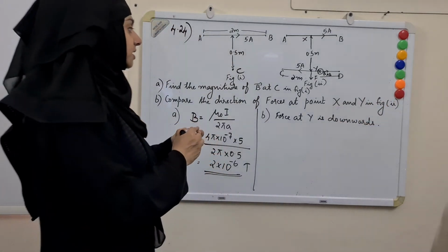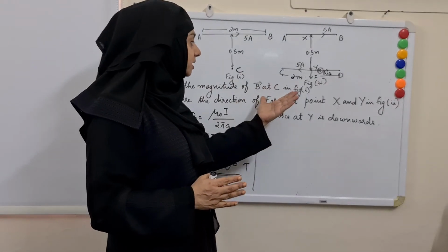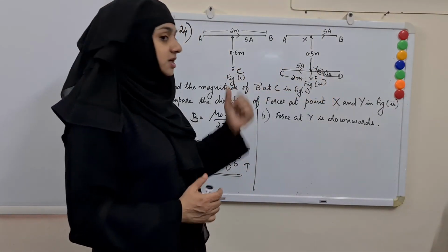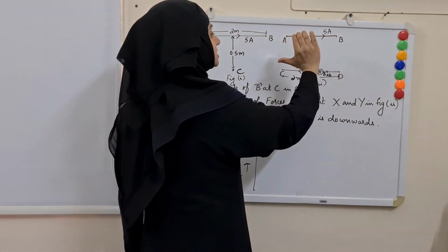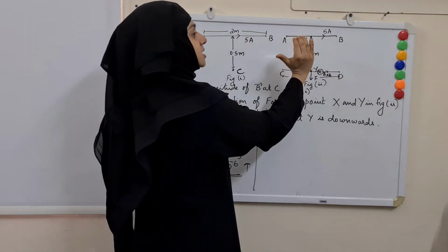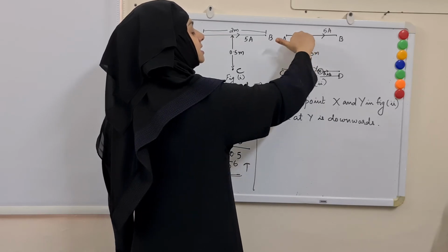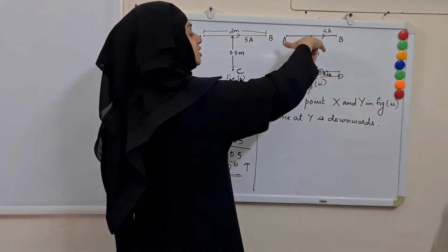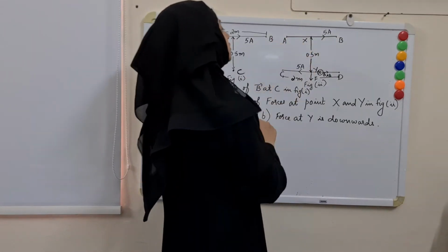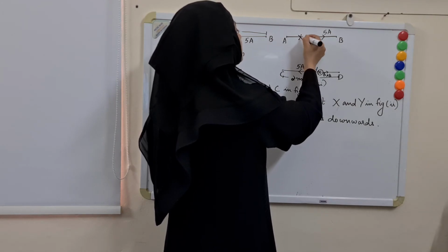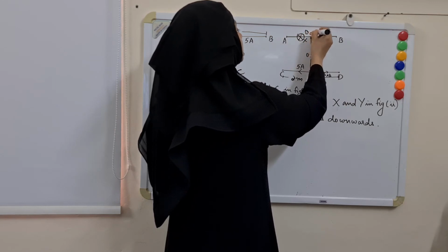Okay. Now let us find what is the force at X. So we will use the same idea. Current is flowing in CD, so I have to take my right hand, point my thumb in the direction of current. See, my fingers are curling like this. So at AB, or at X, it's going into the whiteboard, or into the paper if you are drawing this in a paper.